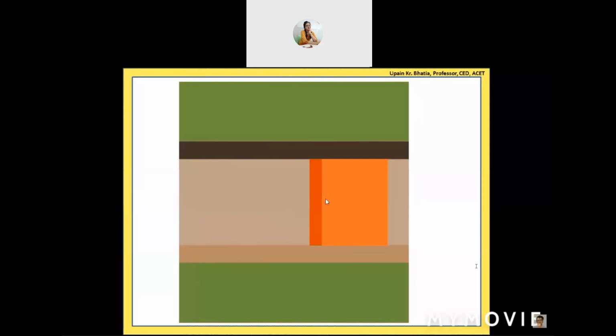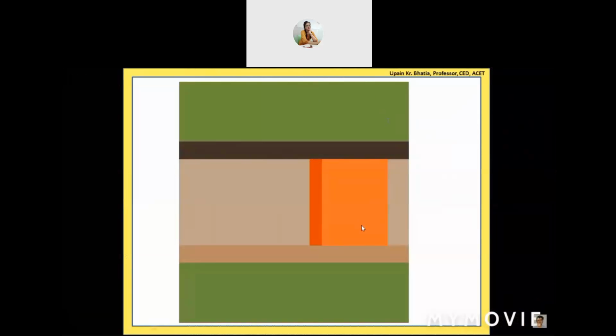So it is not depressed all of a sudden. From here it is the canal bed, and from here it starts gradually going downward up to this level, and we maintain a horizontal depressed floor up to this point. This is basically done in concrete to secure the depression of the bed and the ramp also. We provide everything in concrete, a concrete floor in this fashion.